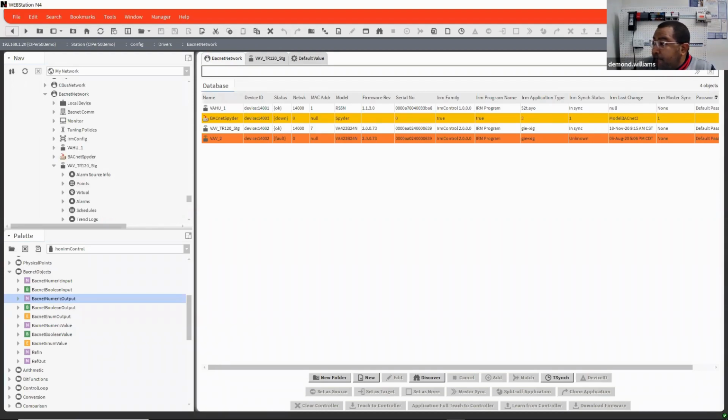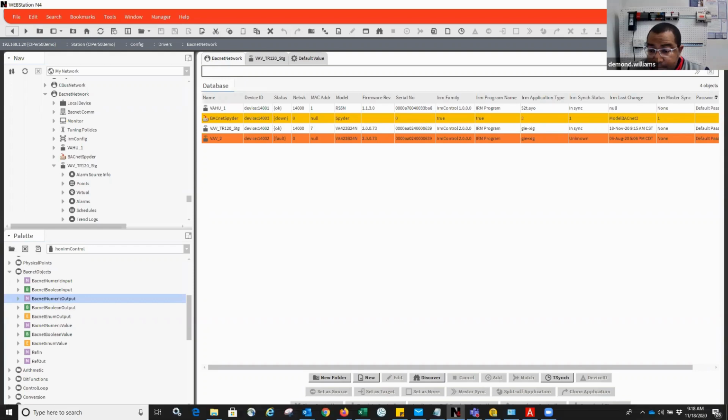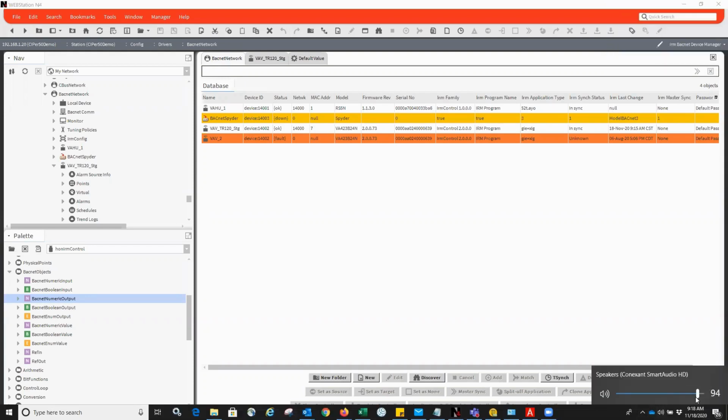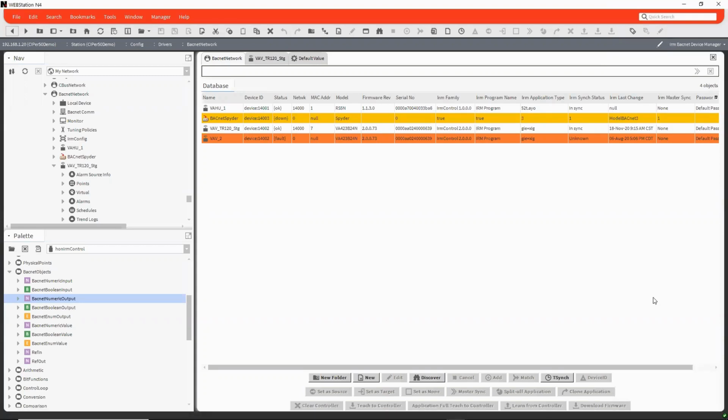Hey, Damon. It's Daryl with AJ Miner. There were a couple of things we saw on the templates. This is just something for everybody. When you change from absolute to relative, you got to really make sure you change the set point low and high, or it will really mess with things.